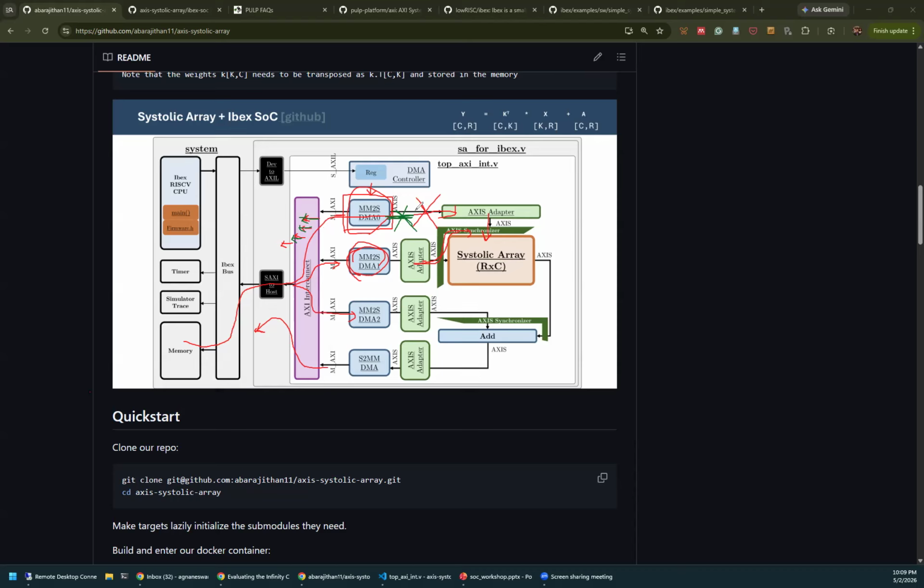Now the DMA has a lot of outstanding transactions. So on this side, what happens is that the SXC takes the data and gives it back through the read data port, right? And now the DMA can't accept the data, because on this side the stream is blocked. So the DMA can't accept the data.